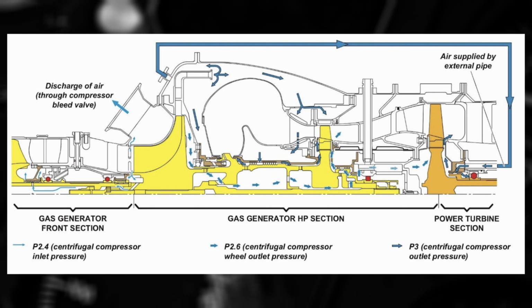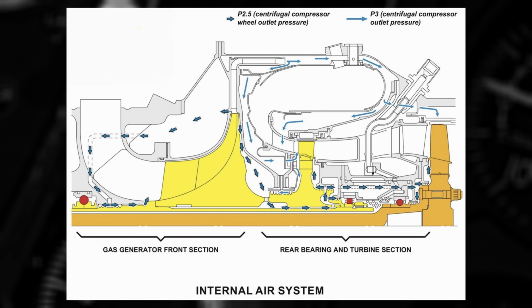It pressurizes labyrinth seals, balances the rotating forces, dilutes and cools the combustion gases, stabilizes the flame in the combustion chamber, cools the nozzle guide vanes, turbine faces, the turbine shaft, and the turbine shroud.